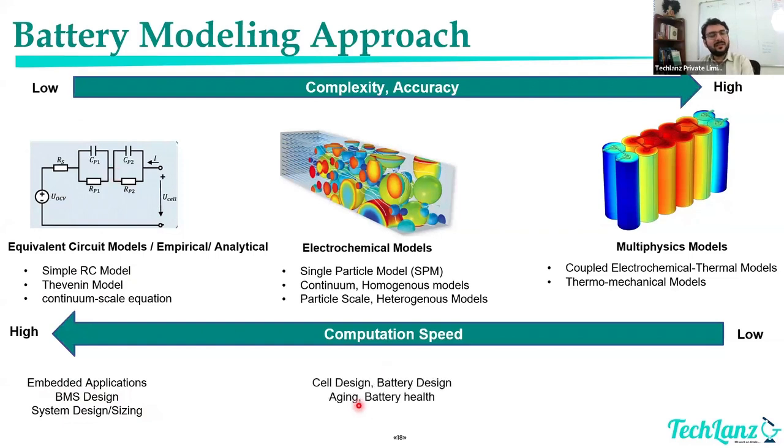When you go for complete cell design or battery design, or aging simulations or battery health simulation, you go for electrochemical models. When you have to furthermore design a complete cell or battery from a mechanical perspective, or perform complete detailed system design, how my system will behave, especially for four-wheelers with very complicated liquid cooling circuits, right? Will there be thermal shock or not, how will my system operate when you have too much vibration, and different DC fast charging conditions, especially in megawatt charging systems. That time the multiphysics models help.